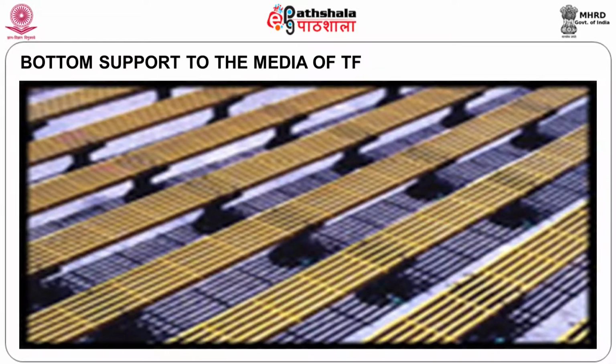In any biological system, the relative rate of mass removal is related to the rate at which the organic matter enters the system and the rate at which oxygen is transported into the biological film. Here the transport is by the diffusive mechanism only. Diffusion cannot be aggravated here, because whatever oxygen is transported, is by a natural mechanism only.